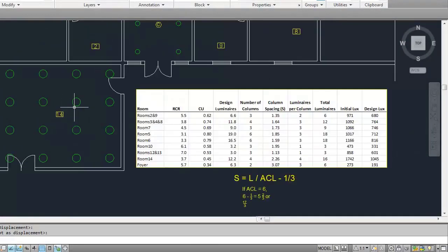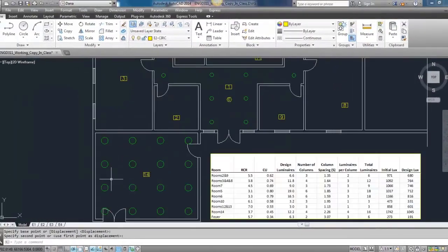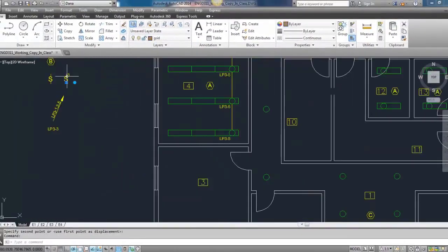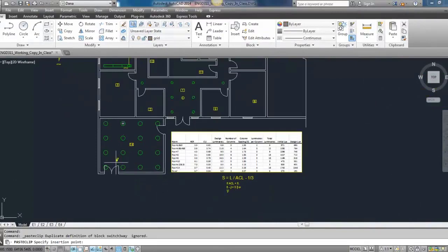Now, again, these lights are metal halide. They are 250 watt luminaires. And because they have such a high wattage, you're going to need 2 circuits for this room. And so you're going to have 2 sets of 3-way switches in this room as well. So let me just show you what that's going to look like here.